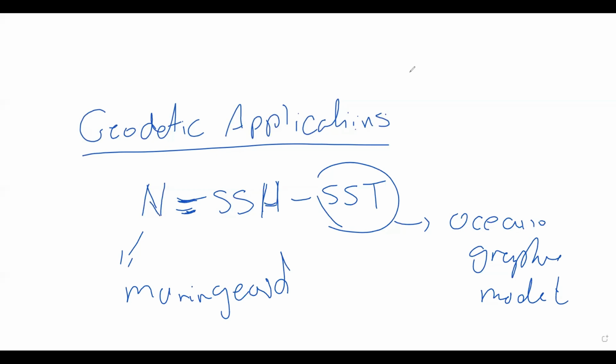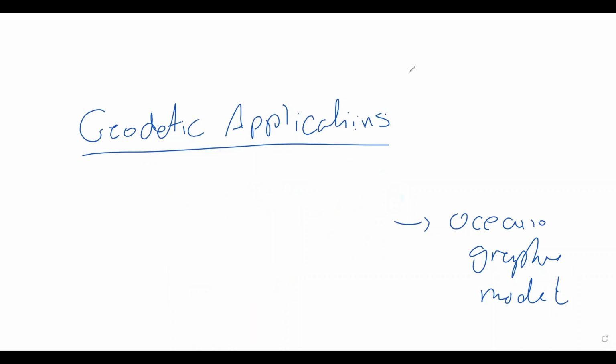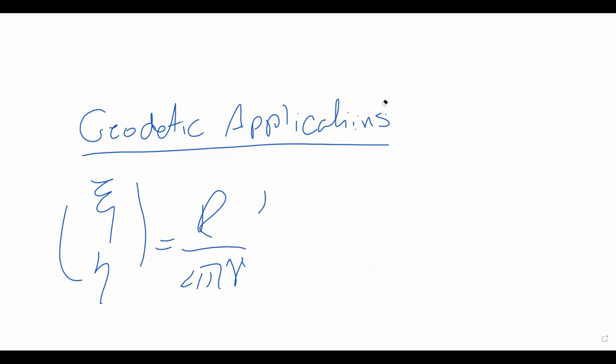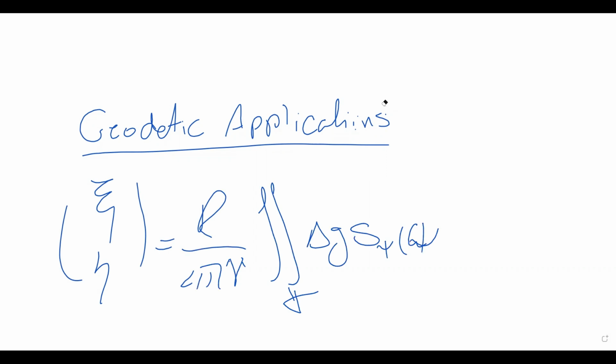So based on this marine geoid that we have determined point by point over the ocean, we can also compute deflections of vertical. If you remember in physical geodesy, deflections of vertical, which are xi and eta, are computed by this 1/(4πRγ) Stokes integral over the Earth, of delta G, which is gravity anomaly, and this is the derivative of the Stokes function multiplied by cosine alpha, sine alpha.